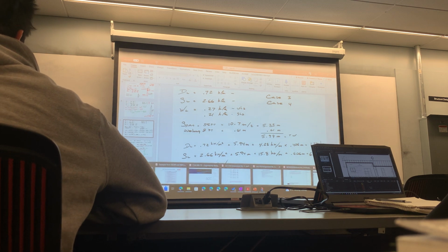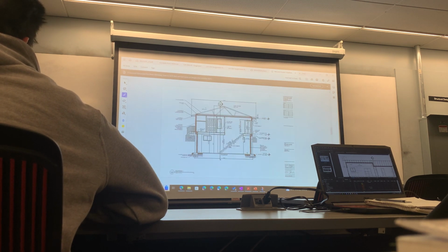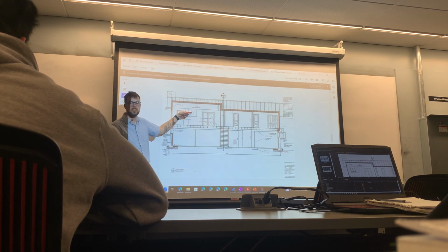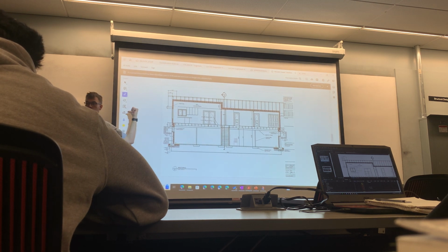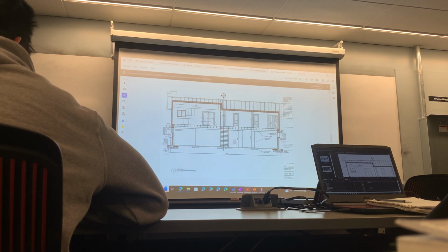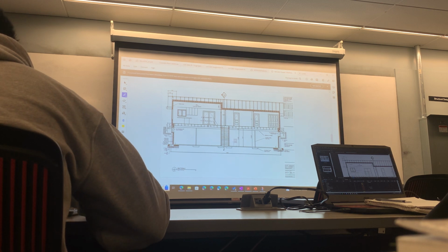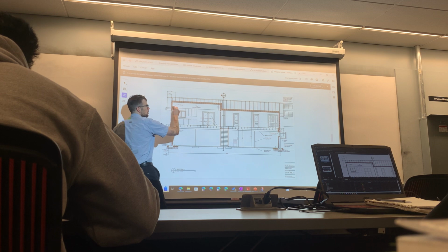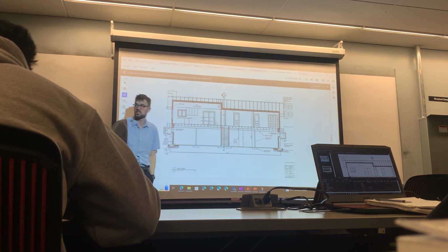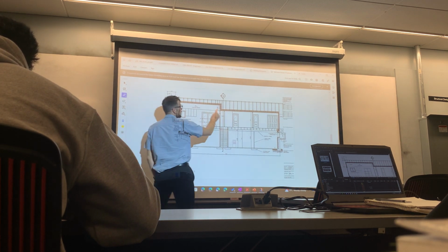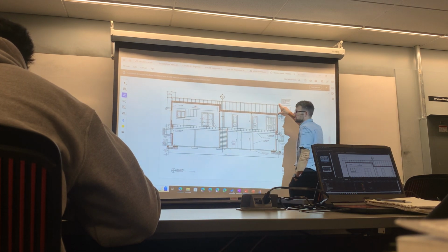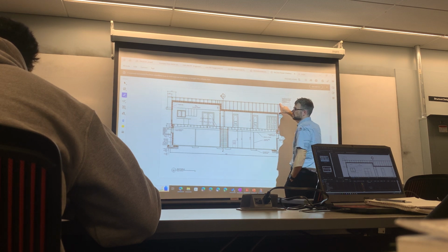So when we look at the vaulted section here, this wall is trying to push in towards the window. What's going to restrain it? There's nothing, right? So when you have these trusses, you can either put a huge beam across the ceiling, which defeats the purpose of the vault, or if you can get it into this roof, then you can distribute it into the roof level here.